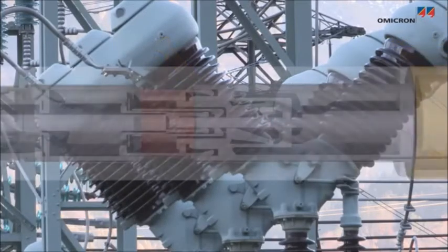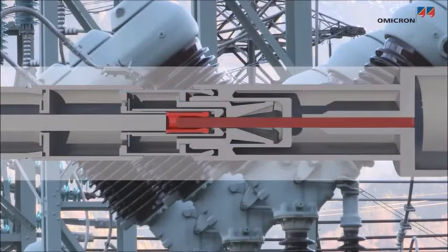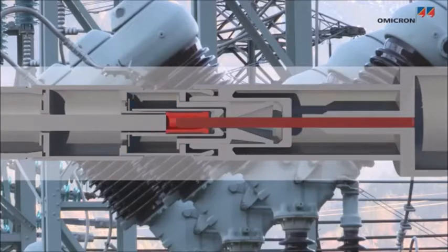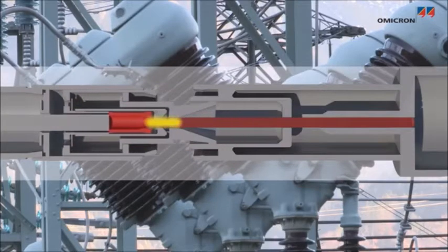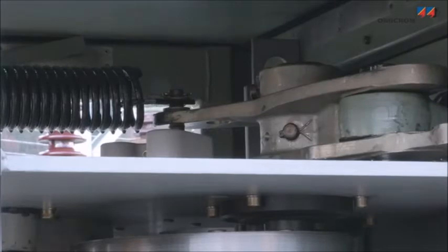Circuit breakers may use multiple contact systems consisting of main contacts and arcing contacts. The main contacts allow operating current to flow with minimal losses, while arcing contacts can break short-circuit currents with minimal arcing erosion. The breaking element is usually operated mechanically by a stored energy system.